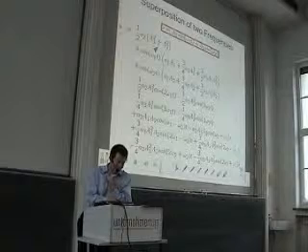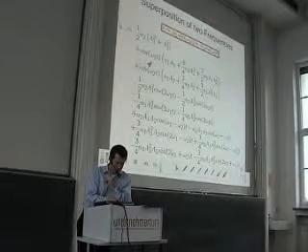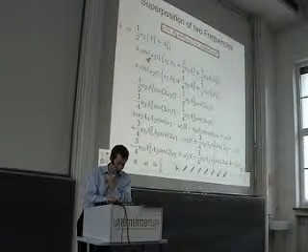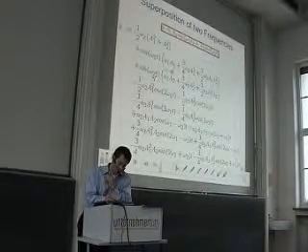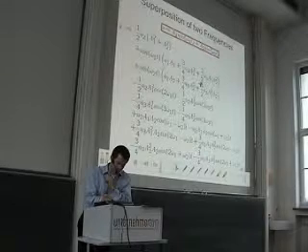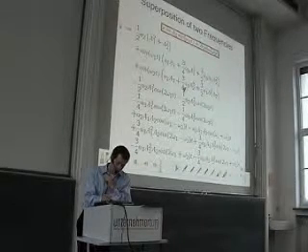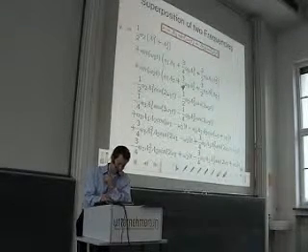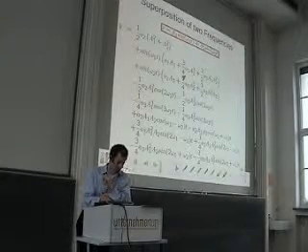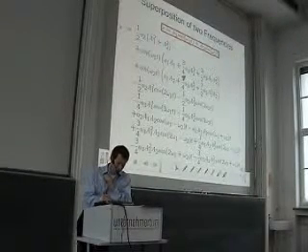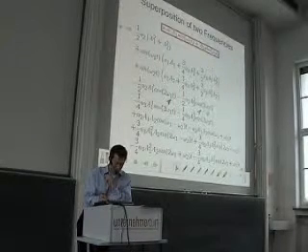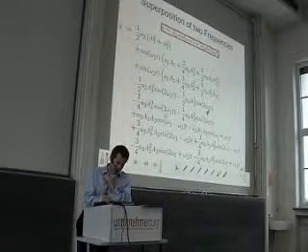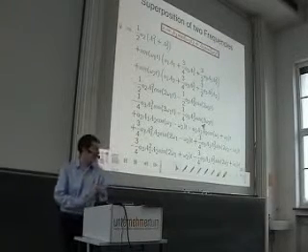Then we get a component of the first frequency and the fundamental of the second frequency, with a huge awful term here, and you can see there is also this effect of the gain compression in here. Then we get components at 2 times the 2 fundamental frequencies and 3 times the fundamental frequencies.